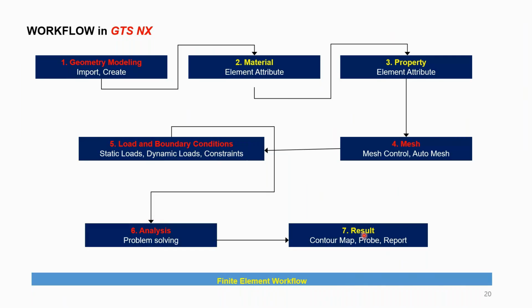So here if I use the tunnel wizard, these steps which are highlighted in red, like the geometric modeling, mesh, and load and boundary conditions and the analysis stages, are handled automatically. Tunneling projects may have different stages as per the excavation sequences and the installation of support system, so then the automatic creation of those construction stages.